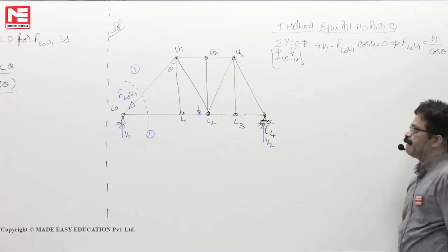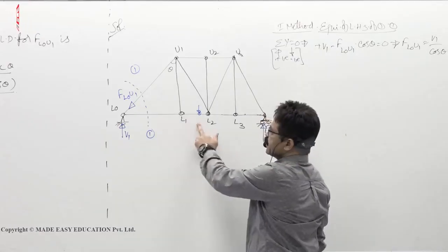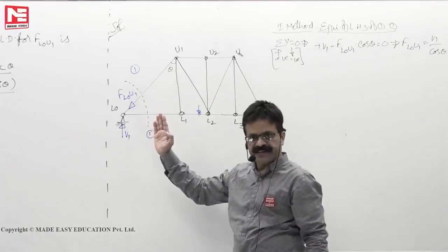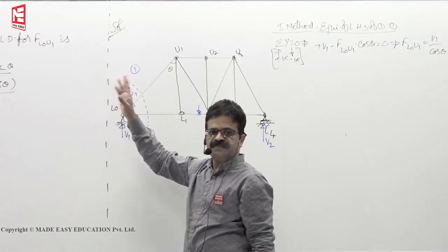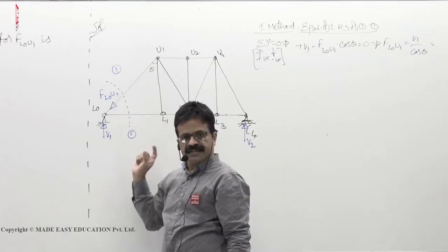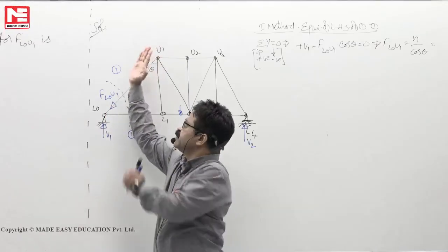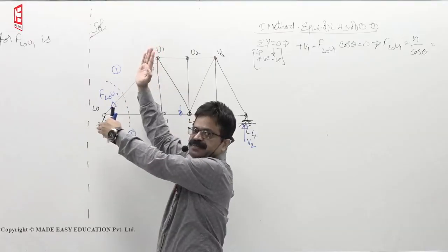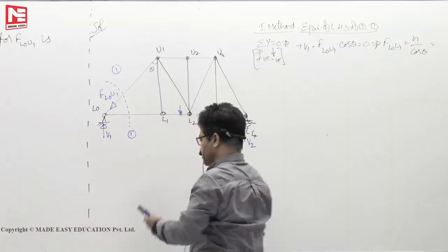How to read V1? I told you about the panel shear. First panel, second, third, fourth panel. In the first panel, if you want to find panel shear force, stand on the panel, look one side. Unbalanced vertical force is the panel shear force. Such panel shear force is resisted by the diagonal members only. So cut left side, upward force is the unbalanced vertical force. So V1 I will read it as panel shear force.